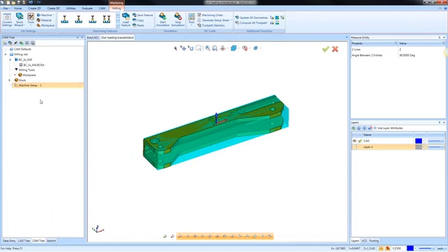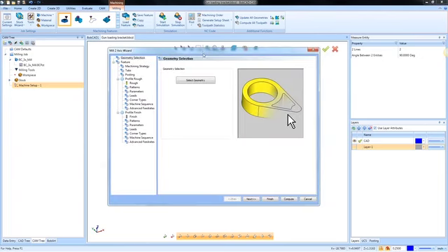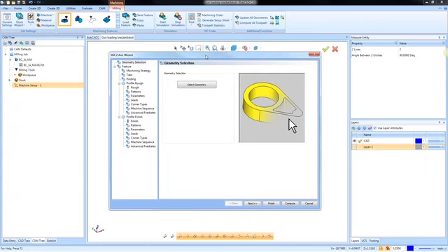Okay, in the V31, you can actually go to this section right here. These icons represent the different machining features that you can create. There's a little arrow down and arrow up, so you can pick through to which ones you may want to select. This first one here would be the mill 2-axis routine, so we can choose that option there. Okay. All right. By clicking that icon there, it will start the mill 2-axis wizard.